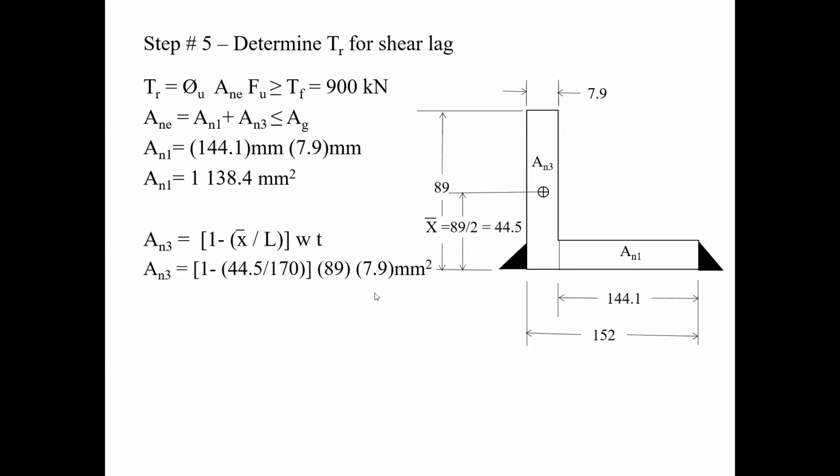And basically, like I said, I've seen people take the centroid here, and they take the centroid here, and of course this is a triangle, so you have to remember this is 1/3, and therefore the centroid of this weld happens to be, if this is 6 millimeters, this is 2. Forget about that. Just keep your life simple. It's not going to make an iota of difference at the end of the day. We're not here to send a spaceship to Mars. We're here to build a building.